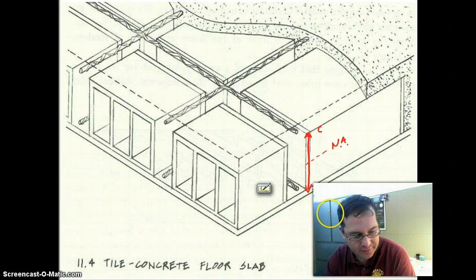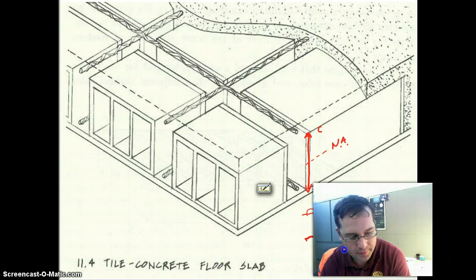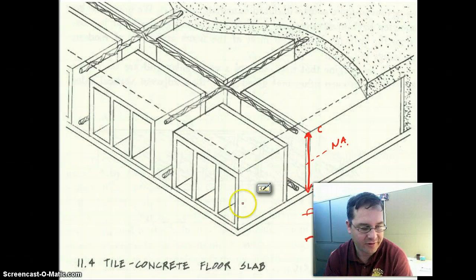But if you think about if this beam were to continue on the other side of this support, well, then it's going to take on this kind of S shape. And so if I redraw the shape of this thing with the supports, it actually takes on a shape that looks a bit like this. Well, on these convex side up parts of the curve, there is tension, and on the concave side down, there is compression. They're getting shorter. And then in the center, on the concave up part, there is compression, and on the concave down part, or convex down part, there is tension.